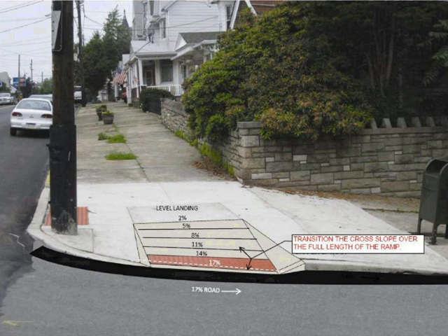It'll look something like this. Start off flat at the bottom and then gradually meet the road grade that you have to meet. It's not expected in an alteration that you reconstruct all your drainage and all your grades on an existing road. And I recommend that you transition to the full length of the ramp, because you don't want any abrupt twists in the cross slope.